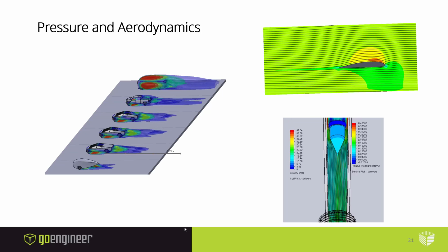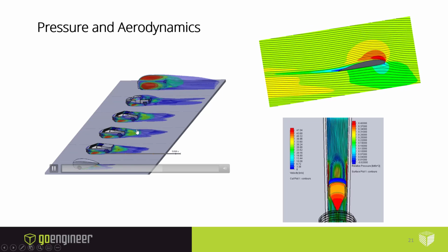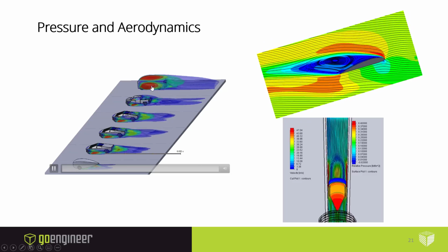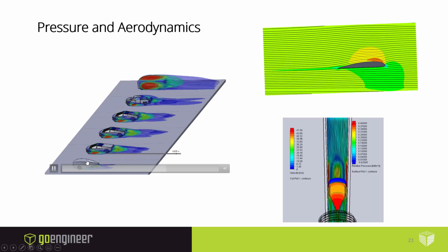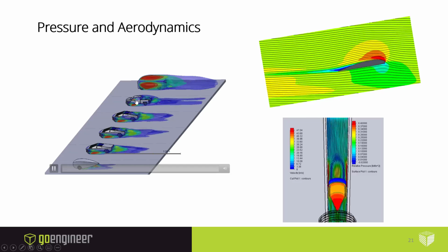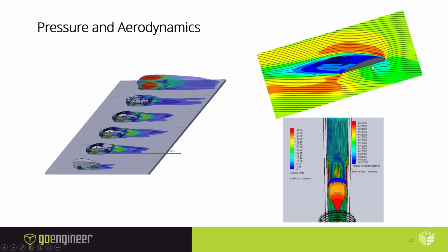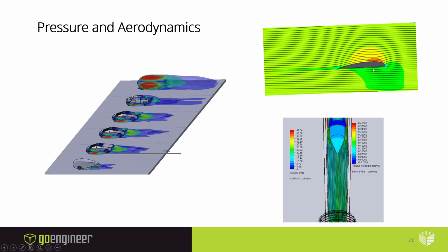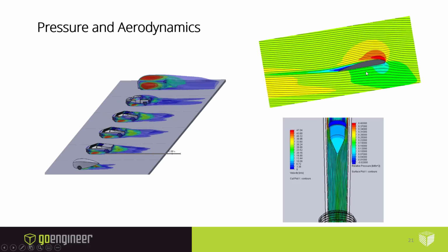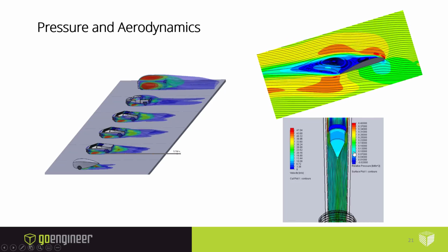Other things you can do with flow simulation. This shows the same kind of thing done at a much larger scale. Here I've got that old Tesla Cybertruck compared to a Chevy Silverado, compared to a bus or a streamline shape, showing different turbulence generated from that to calculate drag forces. Here's an airfoil where I'm actually tipping it a little bit as we go. We're changing the direction of the incoming airstream, and we're seeing at what point it stalls. Right there, it starts to stall at that angle.